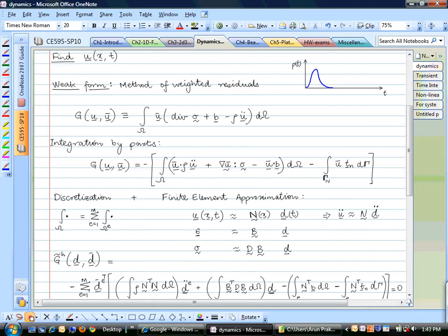Actually this should be a vector, a stress vector, not a stress tensor, according to the Voigt notation. So we have the same thing, B matrix times d and D B times d for the stress and the strain. The only difference again is that all these things are time dependent. These terms are not time dependent, but the result is obviously time and space dependent.